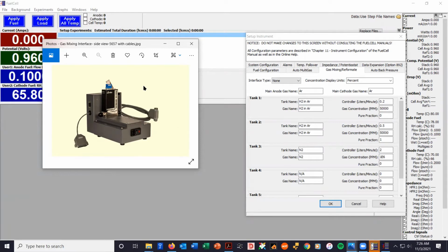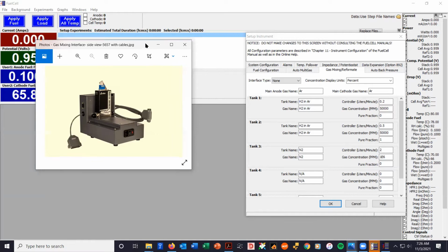And so you have to wait for some period of time until you can go back to testing with pure hydrogen. You recover the cell performance and you go back to testing with pure hydrogen. It just takes a while to get rid of it. So you might want to dump that carbon monoxide in at the cell inlet instead of having to go through the test system, in which case you'd have your gas plumbed to the mass flow controller, and then the outlet of the mass flow controller would go directly to the inlet of the fuel cell, and you'd be bypassing the 850 completely.